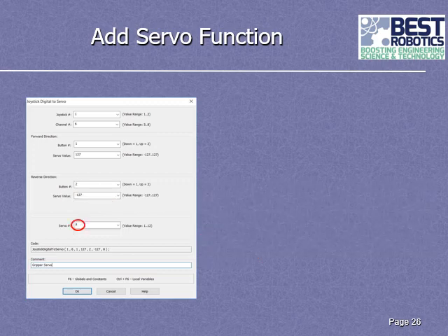And again, you have to pick a motor port, so just pick one that you haven't used before. One good rule of thumb is you have basically ports 2, 3, 4, 5, and 6, 7, 8, 9, so you have like 8 ports you can use. Try to spread them out amongst the first 4 and the second 4. It's kind of a power management thing. I'm not going to go into the details of that, but if you can, especially with the bigger items like the motors, keep them on different sets of 4 just for power management. So in this case, we're picking port 8.